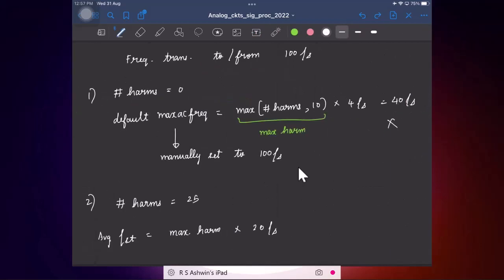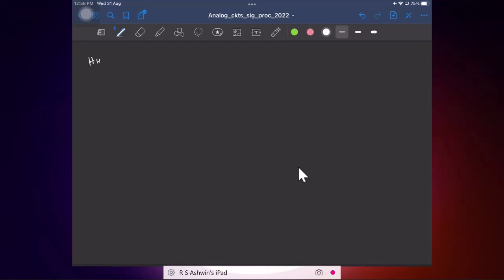That's fine. So this is how you will probably set up the PSS simulator, PSS analysis. So specify the frequency Fs, that is the frequency at which the circuit is periodically time varying, and then you set either one of these or both, the number of harmonics or max AC frequency. And once you have the information about the periodically time varying operating point, then you can find all the harmonic transfer functions, right? So let's say now we are interested in this fellow.